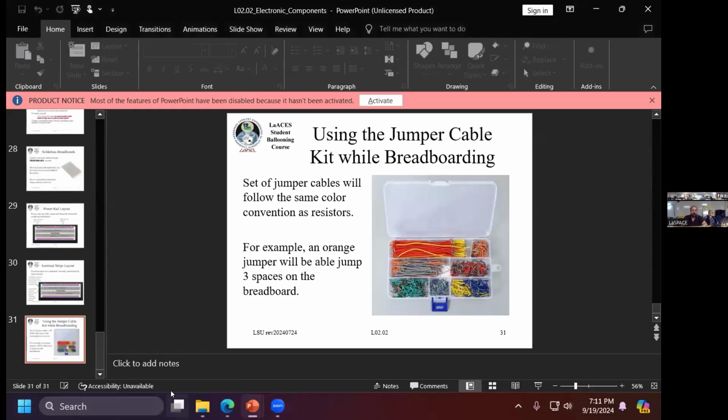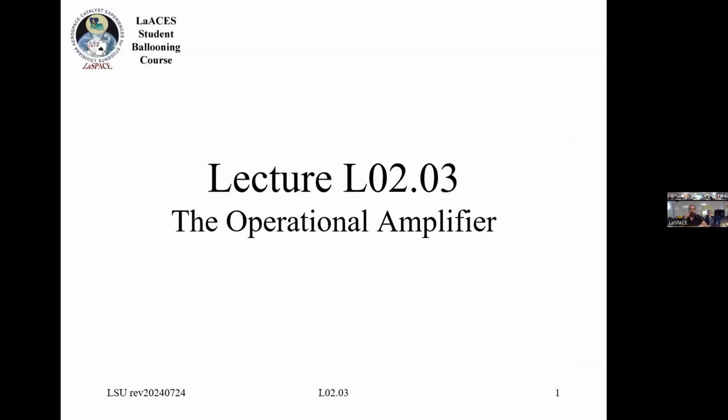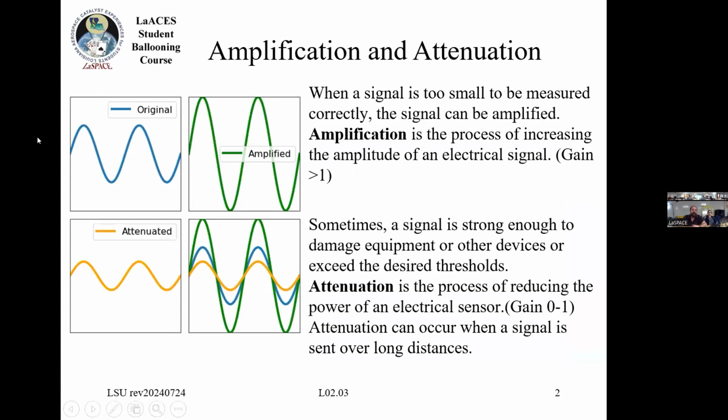All right. So, there's one particular type of integrated circuit that we just want to go over. Typically, the most common thing that you want to do is make a signal bigger or smaller, right? So you want to amplify it. Usually you start with something that's small, and this is time changing just to make it clear that there's something changing, and you want to make it big, right? You have a sensor that is going to change by just a few millivolts, but the thing that you're going to read it out with, you want that change to be in the multiple volts range. So that's called amplification.